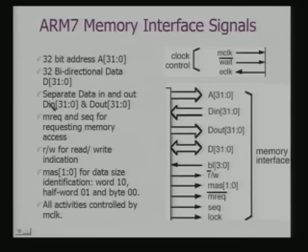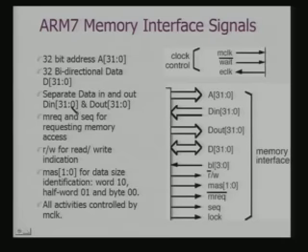Although if it supports separate data in and data out buses, if the external memory explicitly supports data in and data out lines, then you can connect it here as well. But many of the memory modules have a single bidirectional data interface. The M request and ACQ, these are two signals. This is an active low signal, M request.